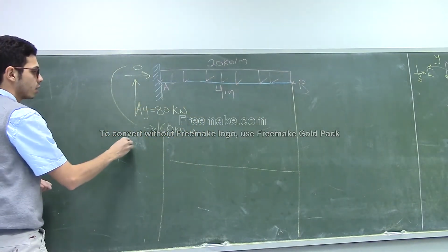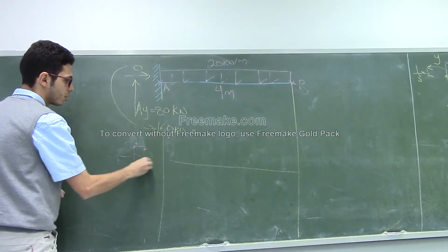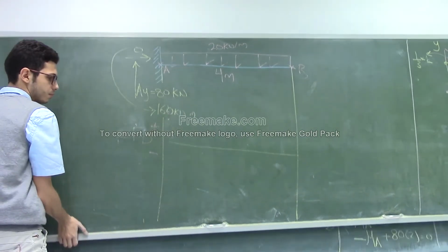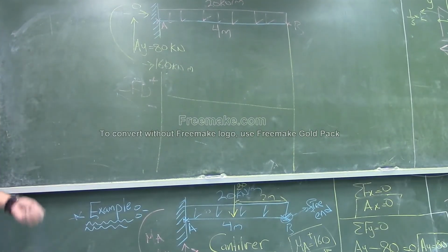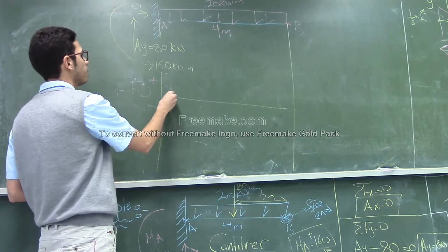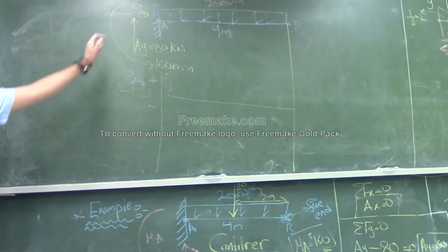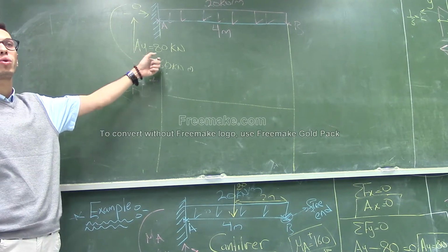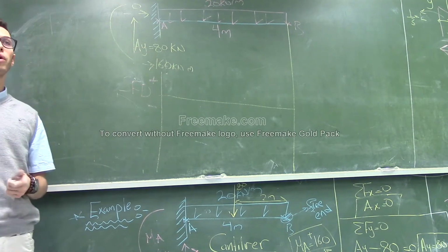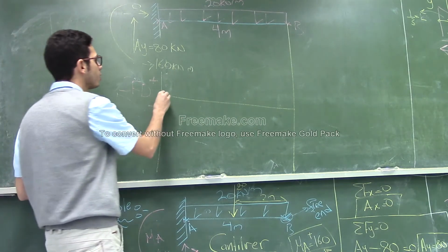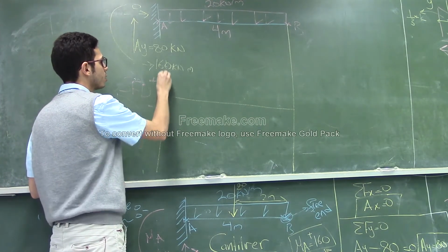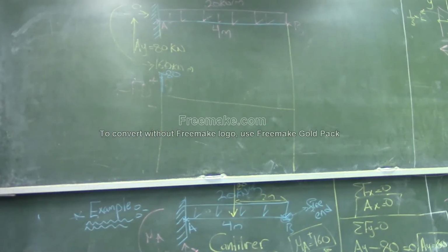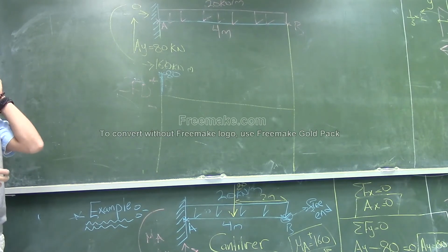Starting with the shear force diagram. Positive, negative. Okay, together. Now at the point A, we have a force on Y which is equal to 80. It's upward, right? So I should go upward here. 8 steps. I go upward 8 steps.